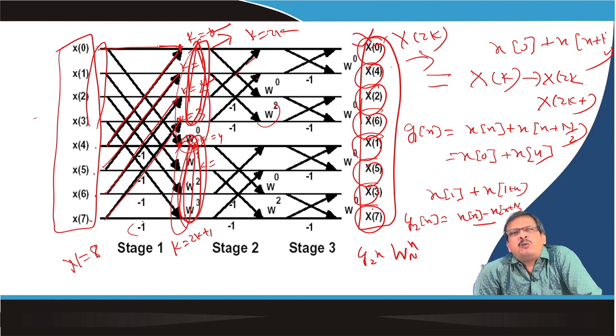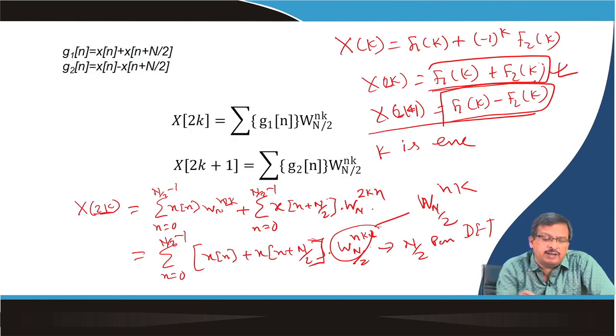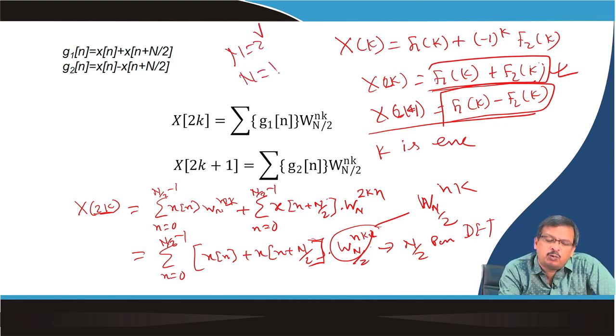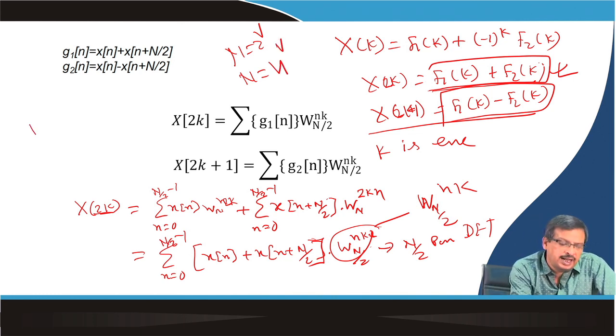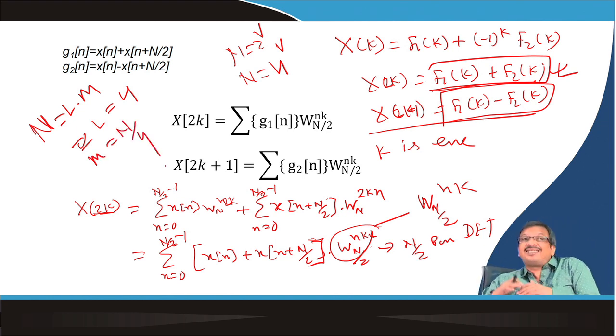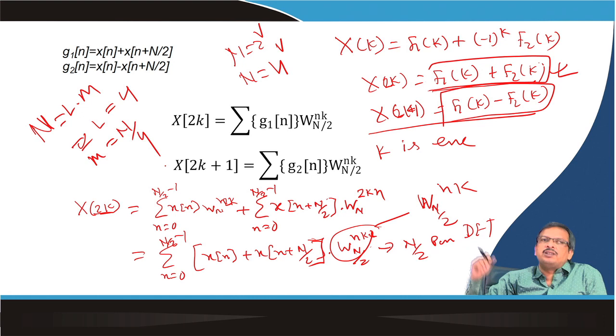Now, if you see, there is a Radix-4 algorithm. What is the Radix-4 algorithm? In the Radix-2 algorithm, I know that n can be expressed as 2 to the power v. In the Radix-4 algorithm, n is expressed as 4 to the power v. So, I can say if n is equal to L and m, and L is equal to 4, then I know m is equal to n by 4. So, instead of dividing n into 2 sequences, I divide the n sequence into 4 sequences.